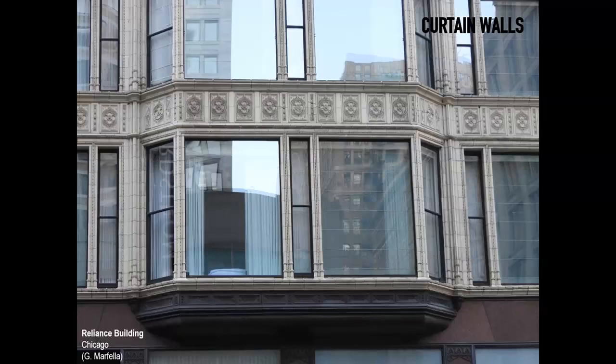The building was also characteristic because it had a relatively lightweight facade, unlike many of the other precedents of the Chicago School. The external walls had no load-bearing capacity, whether to support themselves, let alone to support other steel members. And the facade was completed with these beautiful terracotta tiles, enamel terracotta, so that they were glazed to have a more long-lasting performance.